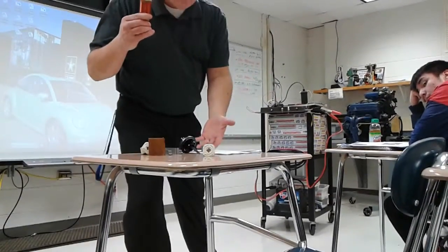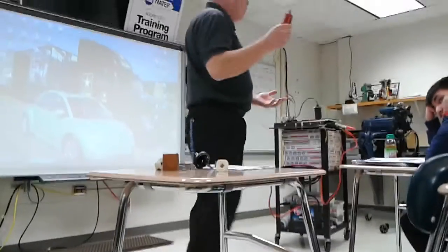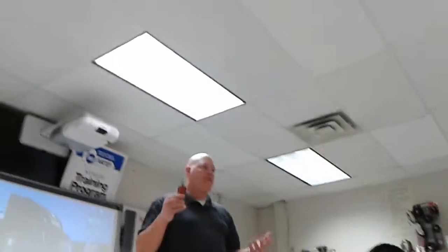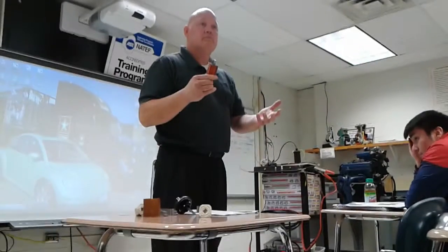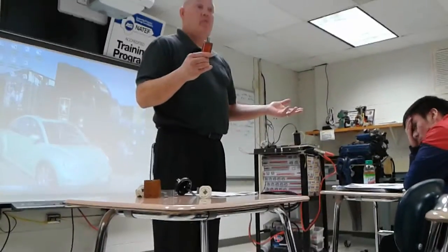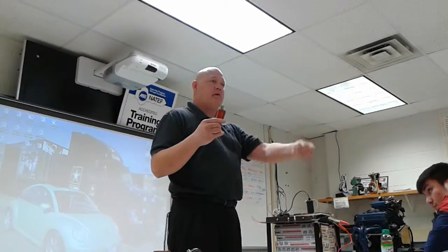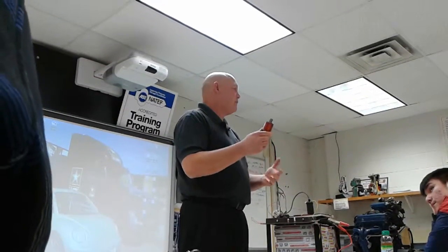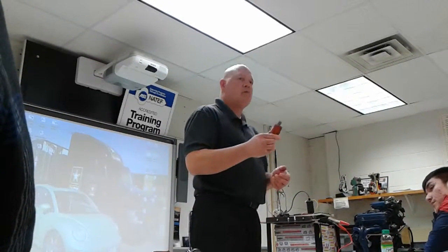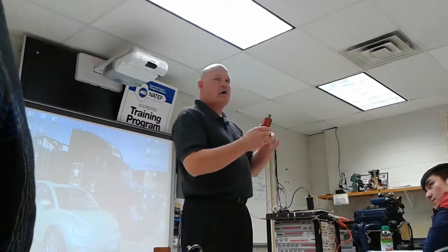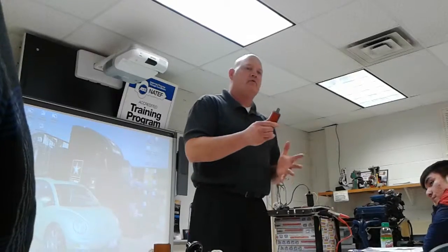How much voltage do we need for a spark? One of the questions there, I think it said something like 30,000 volts. In a car, we're using 12 volts. In your lawnmower, you might be having only a couple of volts. You're talking about a magnet passing over this coil of wire, creating a magnetic field, running a magnetic field over these wires, creating some electricity. You're maybe only making a couple of volts. For a small engine, maybe you need about 5. For a car, we're talking about 30,000 volts. So we're taking 12 volts, and we want to turn it into 30,000 volts. How are we going to do that?